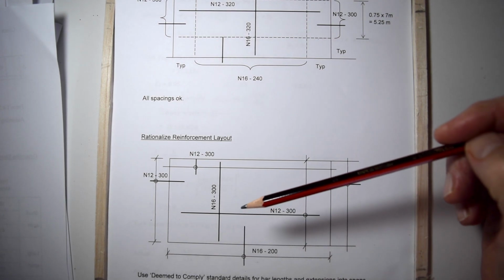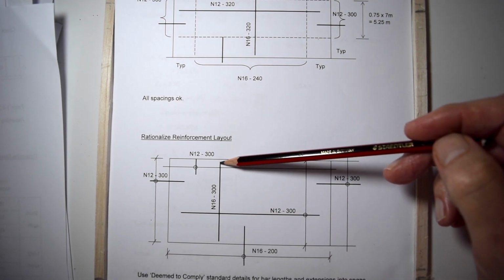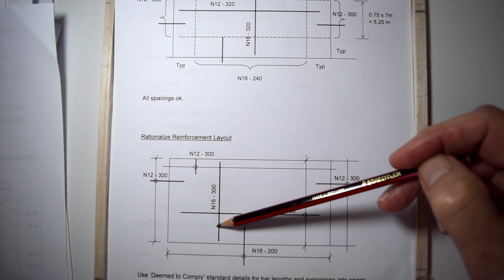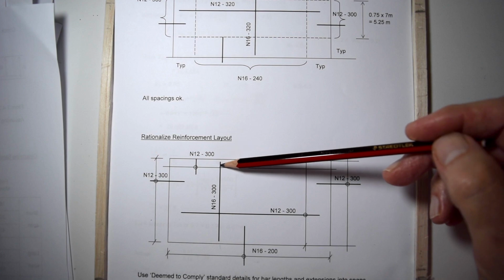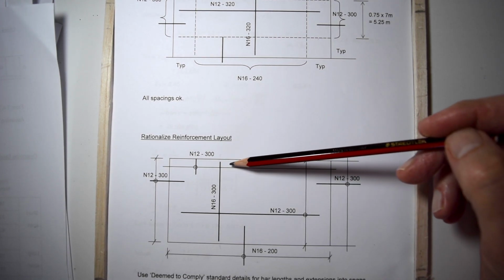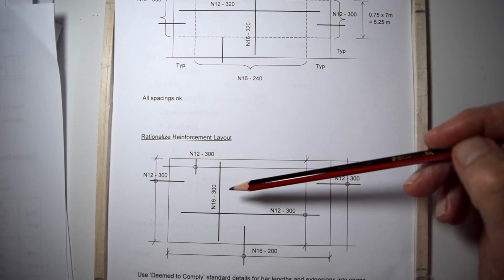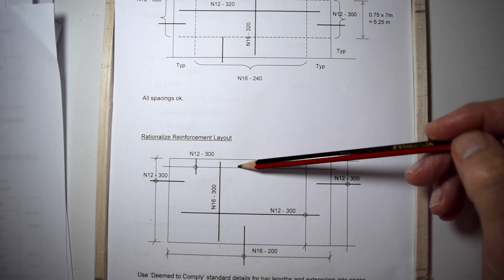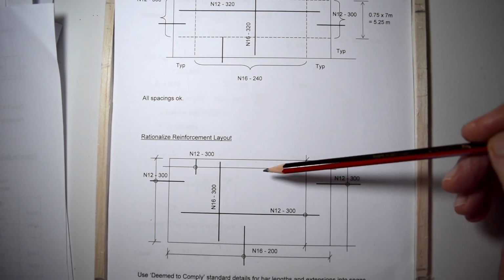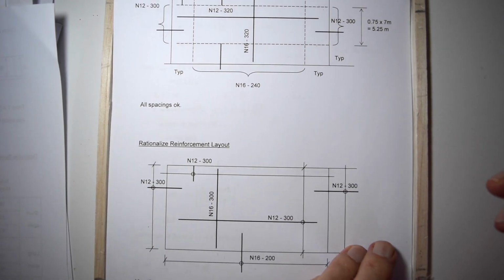As I said to you before, in the one-way slabs, you can carry half of the steel through onto the support and you can curtail the other half. Or what people do is they stagger the bars. They'll run this one bar through to there, the next one 300 away, they'll run to there and they'll cut it off there so that near the supports you're only getting 50% of that steel running through onto the beams.